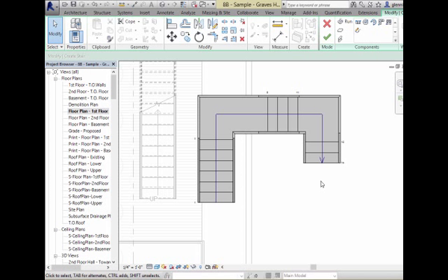Okay. Make a little three-legged stair there. And again, these shapes, it's quite independent now. The issue of the rail and the type of the stair, those are type properties. Laying out the basic sketch of the shape is an independent thing. You can really do that independently. You see 1 through 7 here, 8, 9, 10, 11 here, 12, 13, 14 is counting off the risers for you. Okay, so straight stairs are not too awfully bad.